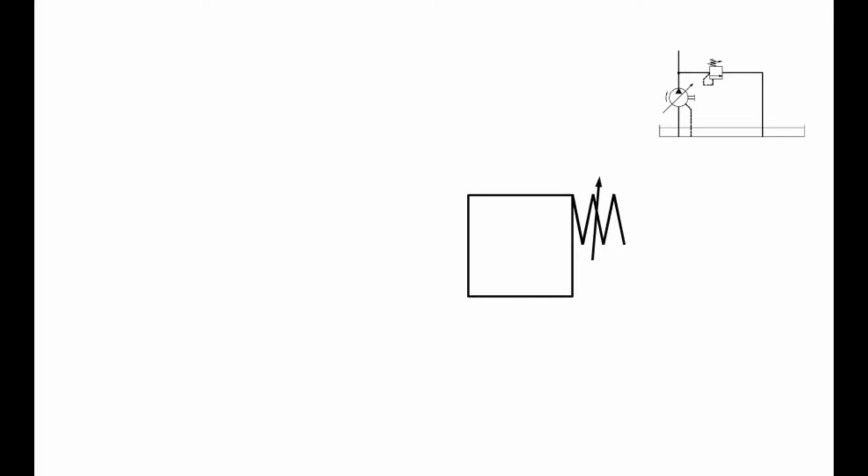The arrow symbol is used to represent adjustability. Spring tension is adjustable, and so therefore is the system pressure at which the valve opens. An angular dashed line is used to denote the pilot control within the pressure relief valve. Fluid in the pilot control line allows the system pressure to appear at the valve seat.